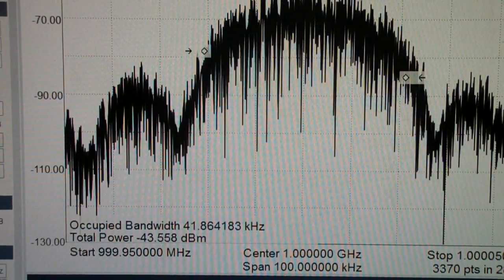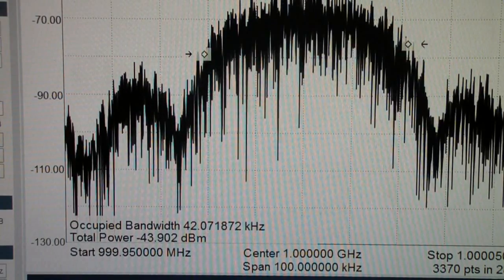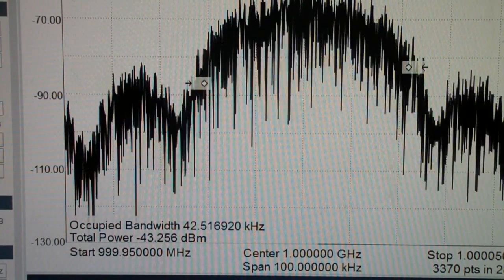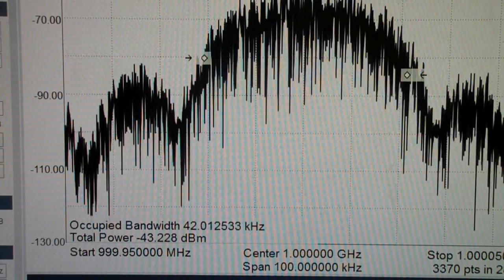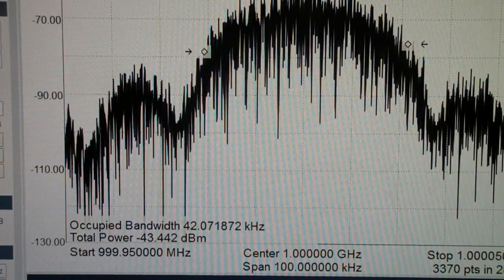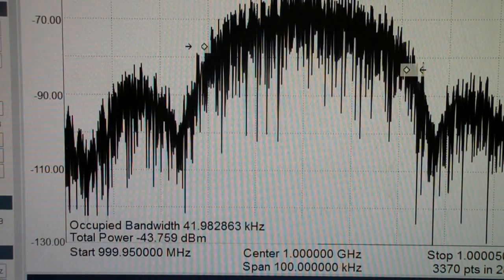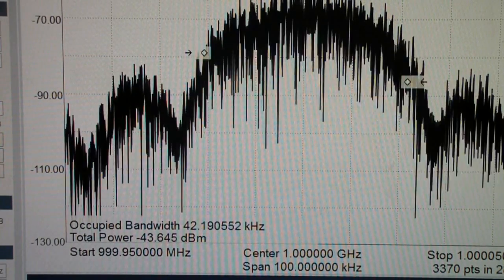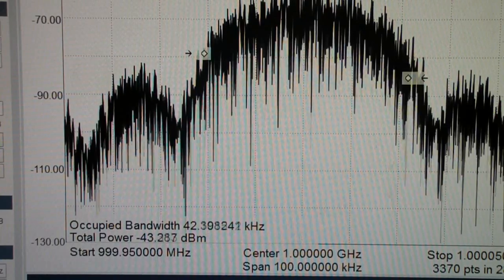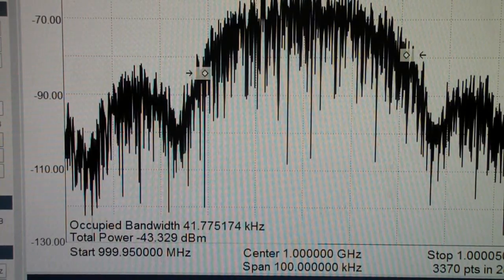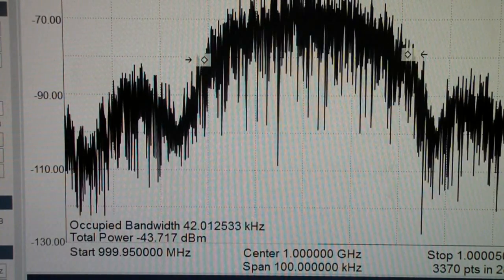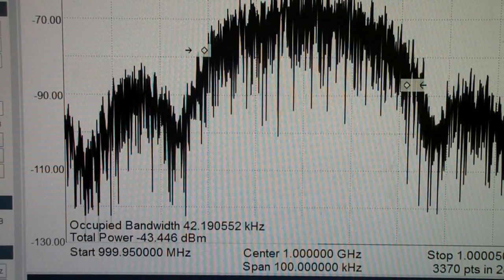Now, for reasons that are historical rather than technical, that method of doing things, that is, using a phase coherent frequency to generate marks and spaces, and then applying a Gaussian filter, has been called minimum shift keying.